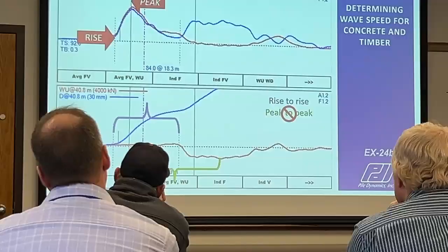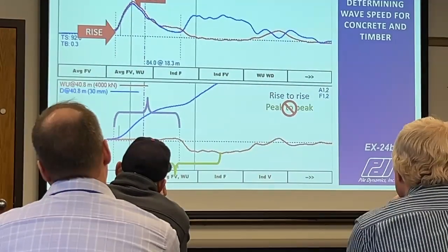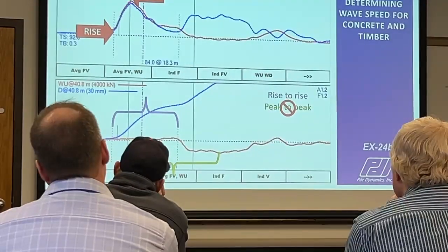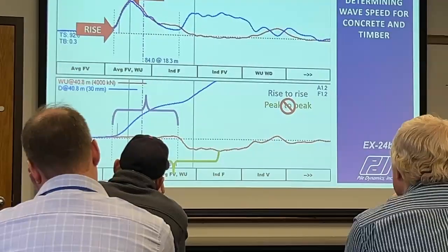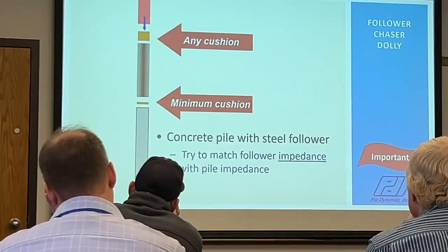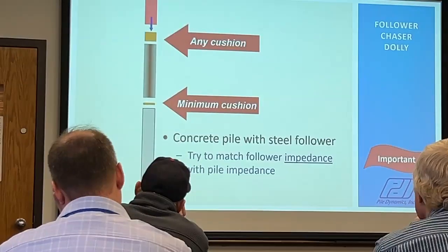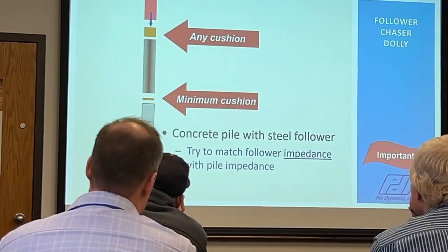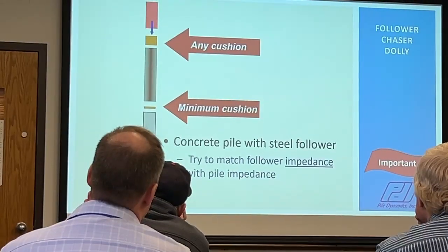And because we've now got a little gap in there, it's having a problem. It's opening the gap instead of transmitting tension up, which is why we have that long flat section that's happening. Any follower drives that are happening in Minnesota? Rarely. Rarely? Good. Makes life easier.